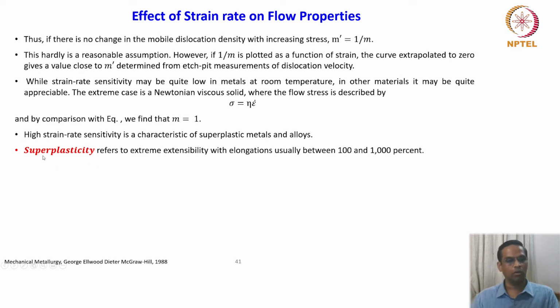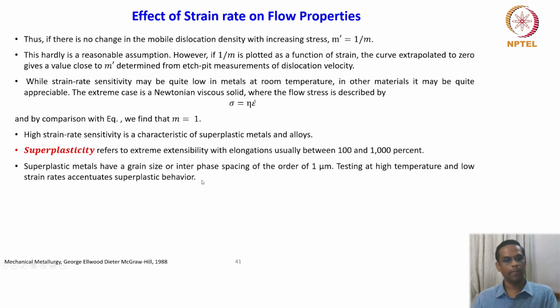We will look closely at the phenomenon when we look at high temperature deformation in the next chapter. But we are just introducing this concept because we are talking about the effect of strain rate on flow properties. This idea comes in because we are bringing in the M value, that is strain rate sensitivity, and high strain rate sensitivity is a characteristic of superplasticity.